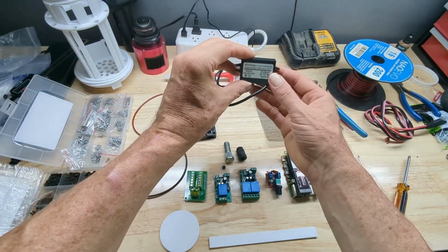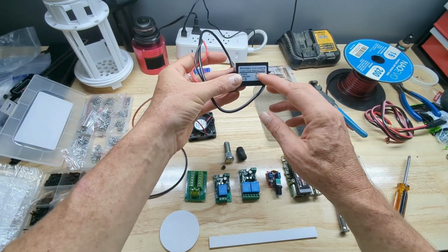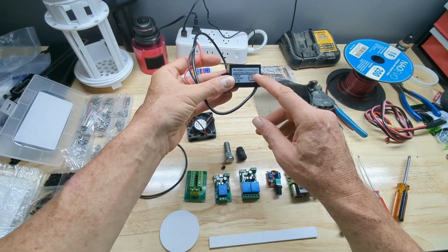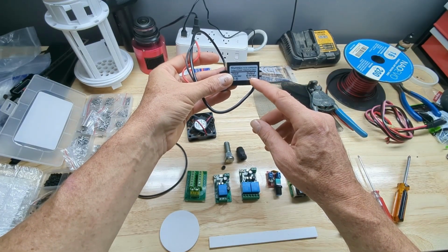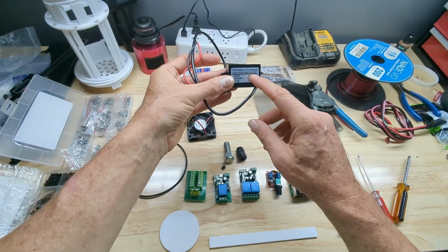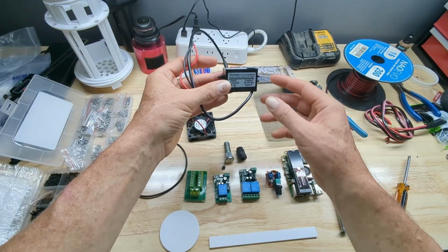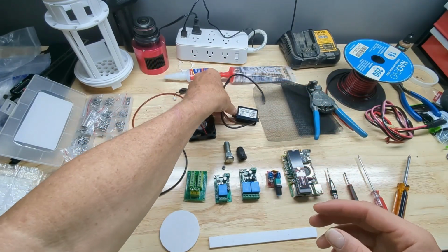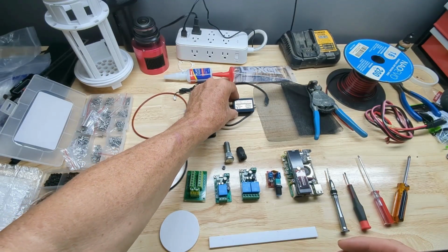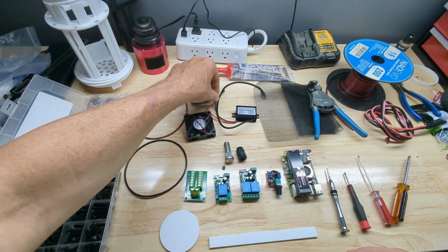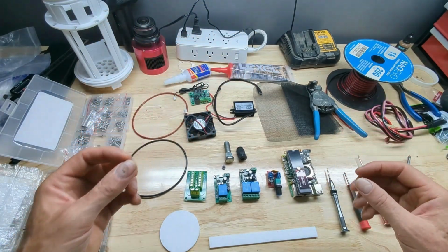This is a buck converter. This is basically what you're looking for on your Pi power supply. You want to make sure that it can put out at least 25 watts and it has a 5 amp output. This is crucial because if you buy a cheaper model, they may only have a 2 or 3 amp output, and it will probably only output 15 watts. If you're using a Pi 5, it will likely reboot throughout the day and night because it's not being supplied enough voltage. So you need to make sure that you get the USB power. It's taking 12 volts, converting it down to 5 volts, giving the Pi sufficient power to actually run.